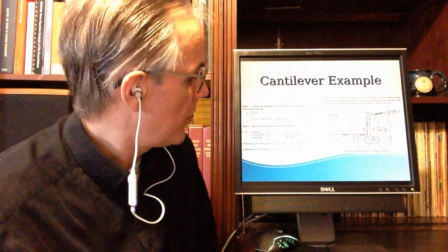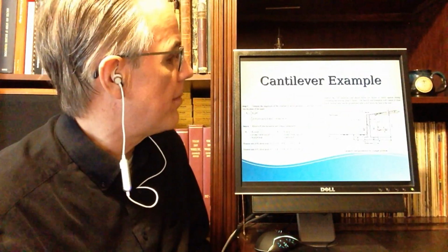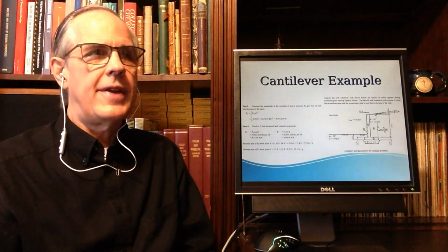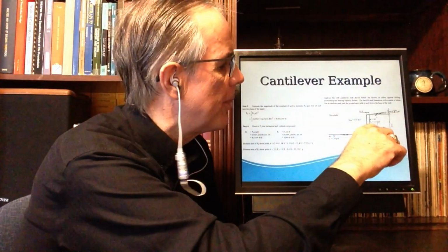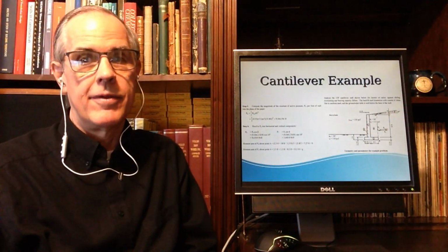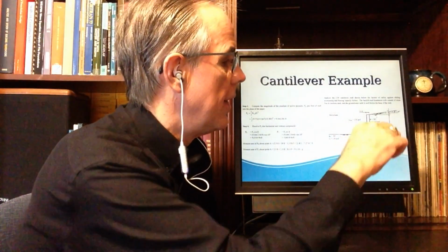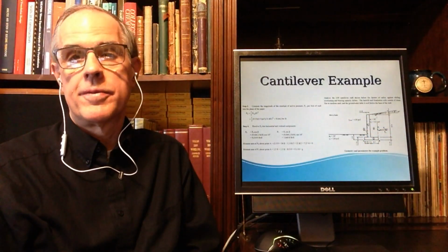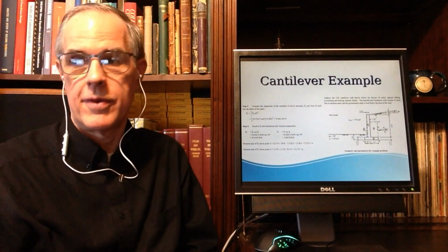So, with that in mind, that's the little g dimension. Okay, so you need to know those two moment arms. This again is where your vector statics doesn't do you a lot of good. In vector statics, we'd have the coordinate for this point right here, and then do the vector multiplication and all that. We don't do it that way for this particular case. We have a moment arm here, we have a force here, it has a moment like that. Notice, interesting, that the moments created by the vertical forces and by the horizontal force are in opposite directions. This is going to be helpful.